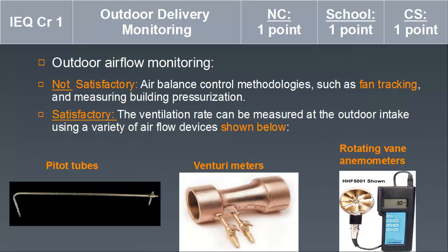There are very strict requirements in meeting the outdoor airflow monitoring criteria for this credit. You cannot use air balance control methodologies such as fan tracking and measuring building pressurization. Instead, you need to measure the ventilation rate at the outdoor intake areas.